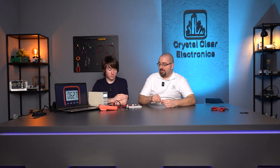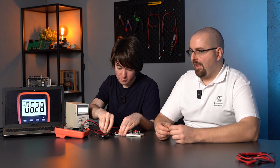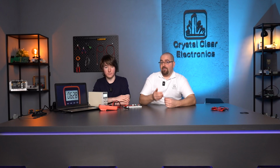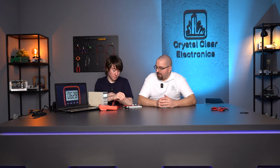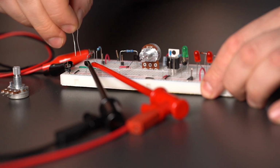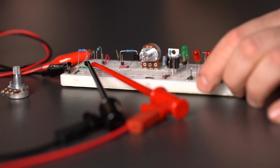To do this, Marcell will take out the 10 kilo ohms load now, and I have a 1 kilo ohm load with me. It means that at 6.2 volts, approximately 6.2 milliamps will flow through this resistor, which is well above this limit of 1.8 milliamps. So, our expectation is that as the voltage decreases, the stabilizing effect disappears. So I'll give this to Marcell to put this load in. In the meantime, our lab supply is already set to 14 volts. I'm going to adjust it a little to make sure it's really 14, while Marcell puts the load in here.